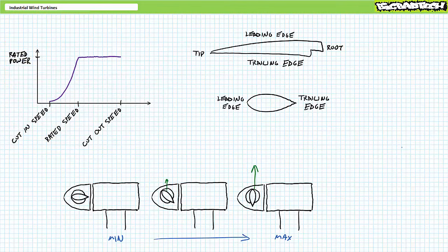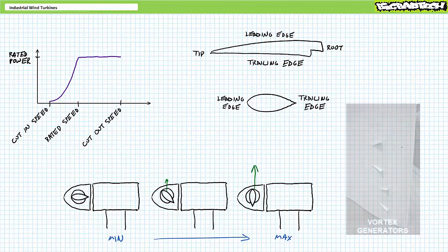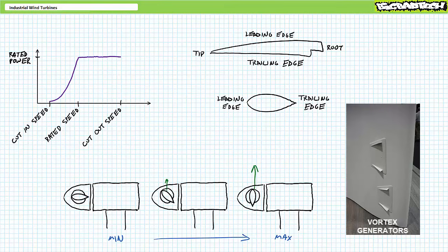Because the tips of the blades are often the highest point in an environment, often subject to inclement weather conditions, inside the blade there exist low-resistance wires which serve as a means of channeling errant lightning strikes to ground. Certain blade manufacturers use accessory aerodynamic devices called vortex generators on their surface that improve efficiency and performance by reducing flow separation, which yields increased torque transfer.